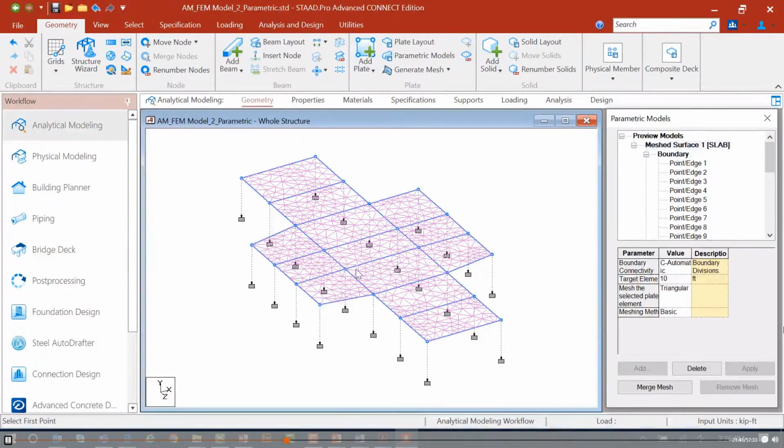And then again, you're going to notice that there are no elements spanning across a beam member. They're connected to all these interior beams and interior columns. When I send this over to STAAD.Pro, STAAD.Pro will automatically segment those supporting members so that they are coordinated with your finite element mesh. They're sharing stiffness, they're sharing loads, and so forth.